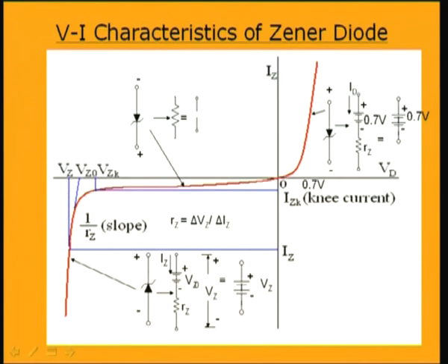Now, again Rz is very small, because this linear portion, if we find its resistance, will be very small, as there is very little change of voltage for a considerably large change of current. So, we will not be wrong if we approximate it to have only the voltage drop Vz naught and ignore this part Iz into Rz. This drop will be very negligible. So, ultimately we have this model of the Zener diode in reverse breakdown as having the voltage Vz, which is equal to Vz naught. So, this part can be neglected.